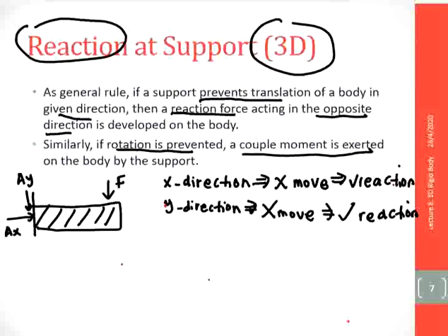Okay, now for the same cantilever beam, there is a force here, and when we apply force, there is a moment, this means moment in the clockwise direction. So here the reaction is in the opposite direction.